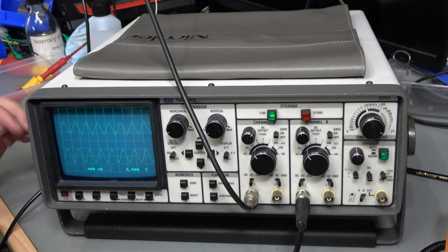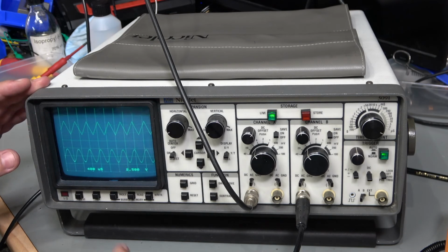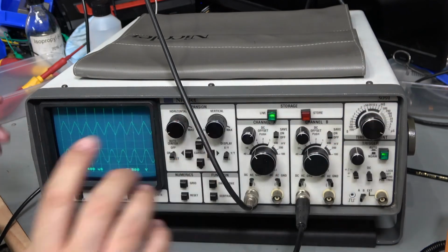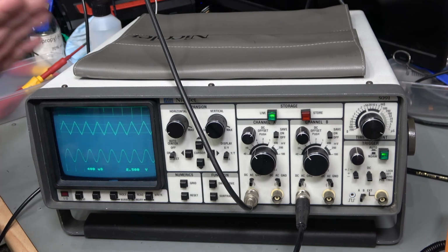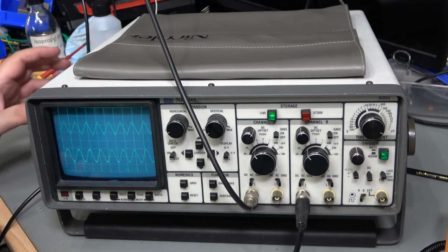Okay, so here it is, the completely repaired Nicolet 3091. This has been quite a challenging repair. The power supply was a bit unexpected, so that uses primary side regulation for the 5 volts, and the plus minus higher voltages used for the op amps and things like that are allowed to just float around. They actually turn out to be running at about 14.3 volts, maybe 14.4, and then on the boards where they're used there is separate plus minus 12 volt regulation for that.